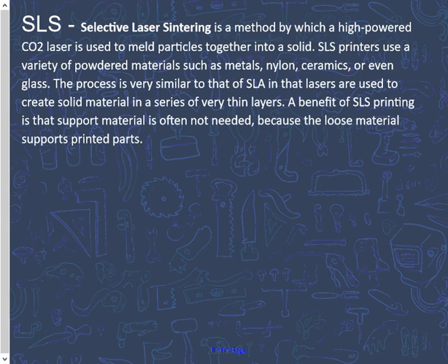And with SLS, you don't need to do that because you're solidifying that top layer, but there's a whole bunch of sandy or powdered material underneath it supporting it, so that the unused material kind of acts as your support material, which saves on a lot of waste.